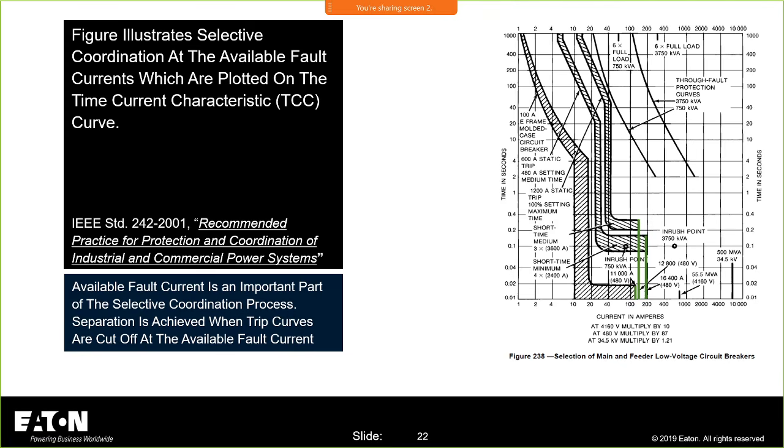Can you explain the multipliers at the bottom of the curve? So those are based on, remember, I'm plotting all of these at different voltages. So you have to do the voltage ratio on whether it's on one side or the other side of the transformer, or depending upon what voltage level you want to reflect these to. That's probably a little bit more detail than we can go into at this point.